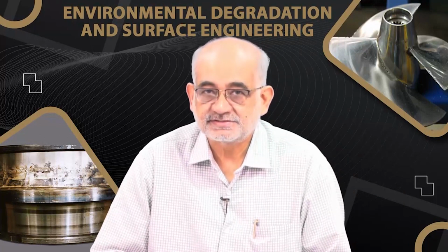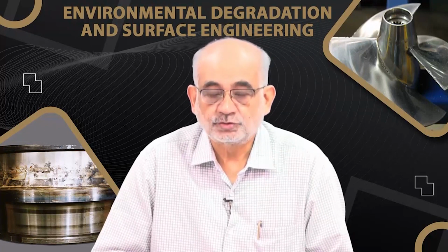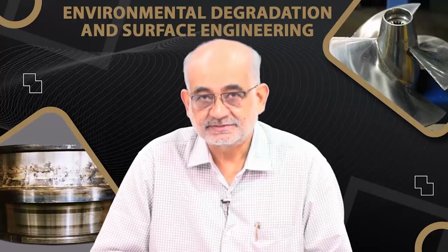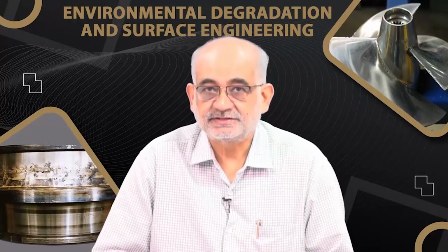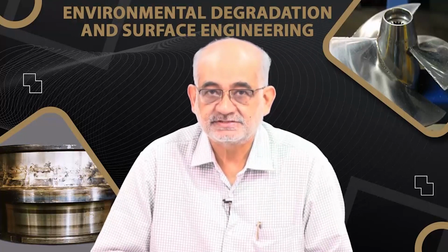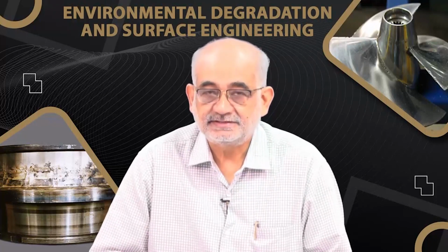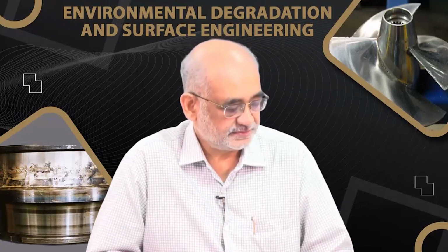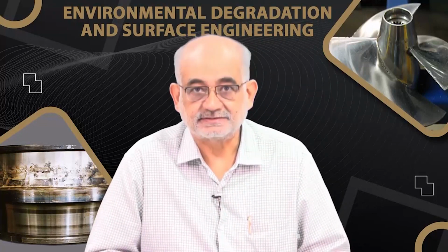circuit. There's no total closed circuit situation like in the case of electrodeposition, where the cations move from anode to cathode and anions move from cathode to anode and get deposited, and outside the circuit we see electronic conduction, and inside the bath we see electrolytic conduction, so a complete circuit. In contrast to that, in these two processes of electrophoretic and electroless deposition, we'll see no such complete electrical cycle or circuit.